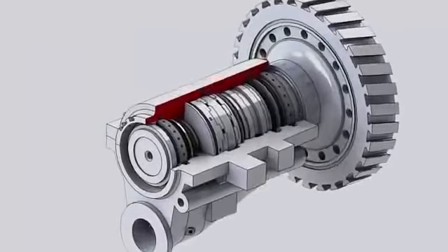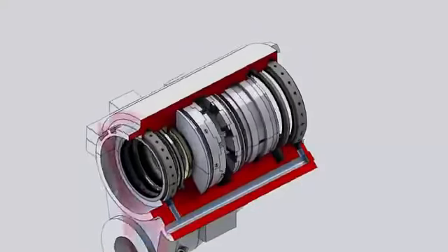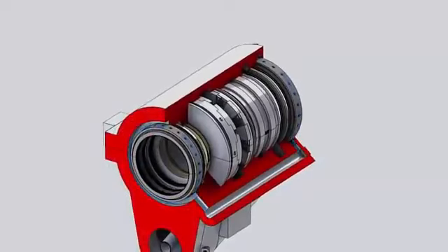The sealing airflow from the cooling and sealing system goes through the axial tube machined at the right side of the housing and is admitted to the labyrinth seals through two ports to annular spaces surrounding the seals.